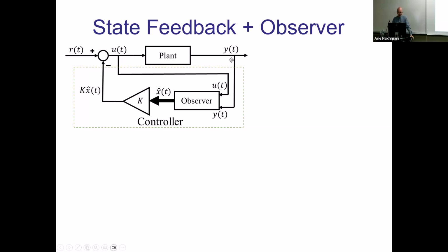Because now your output y will be changing based on whatever input you provide, and this was not the original intent because your control is not based on the original x. Who told you that this will even converge, I'm not saying to the correct thing, even converge, even be stable in the closed loop? Because you're using the wrong x from the beginning.